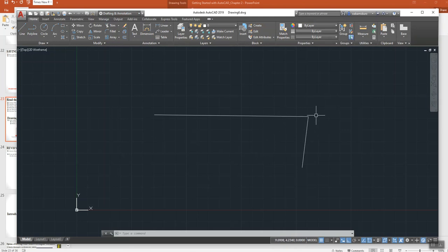the problem that I've run into over the years is if you set your drawing limits, whenever you begin to input text or dimension, AutoCAD automatically adjusts the size based on the limits that you have set for your drawing. So you don't have to scale up or scale down to try to fit the object itself. Everything would be proportional in terms of your drawing. Okay, so keep that in mind.